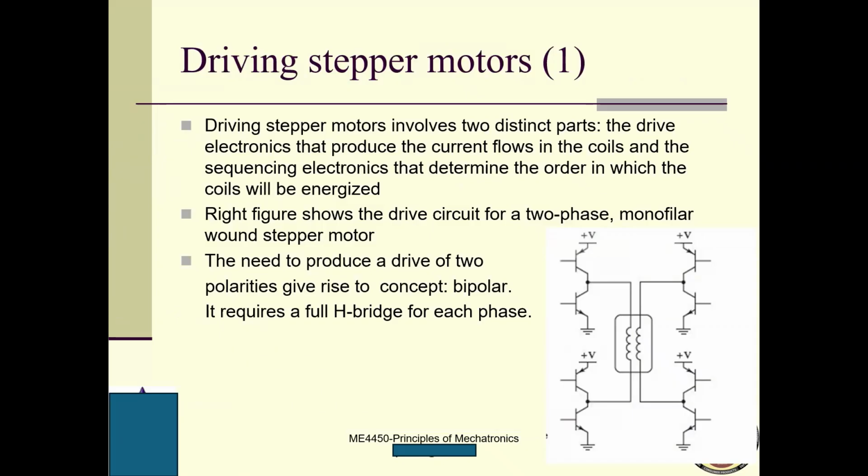So here is driving step motors. So now we come back to see the driving step motors here. This is a step motor. And can somebody tell me what this is, a monofilar or bifilar, guys? Monofilar. Why? Because there's only one coil per pole.